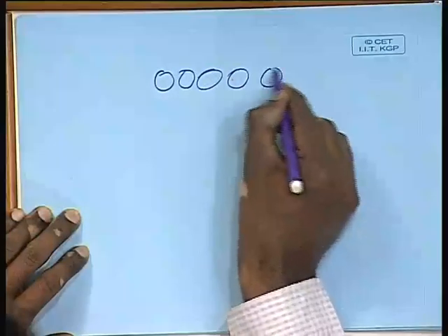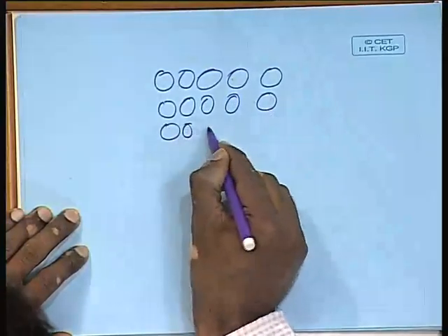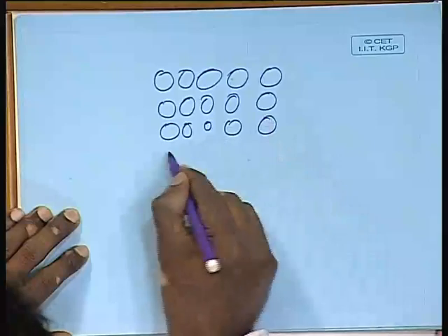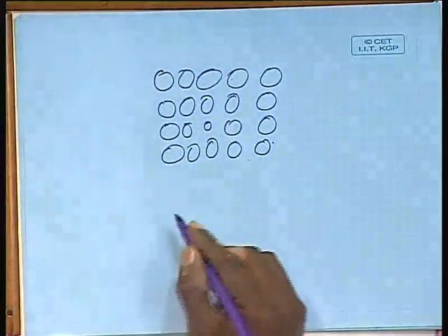Why is that? There is a restriction on the solubility, because whenever a B element dissolves into an A element, we know that the atomic size of B is different from that of A, and as a result when you put a B atom into an A lattice, there is a stress involved. For example, if you look at the atomic arrangement, something like this, A type of atoms, and if you have a small B atom which is not really interstitial but substitutional, but its size is smaller than the